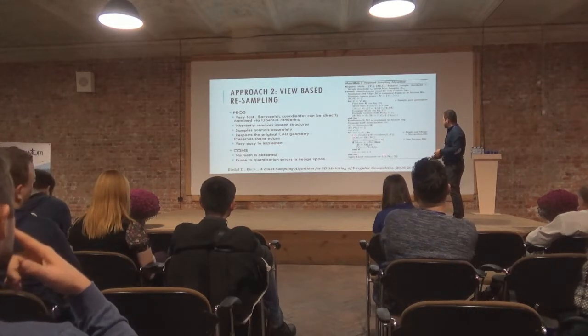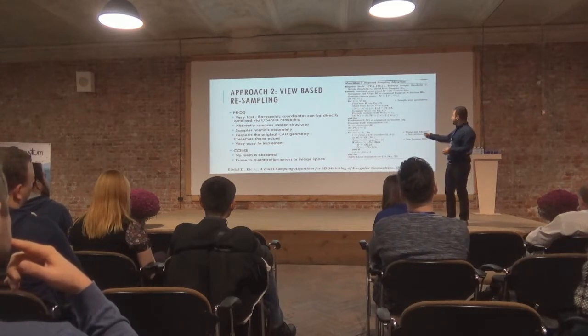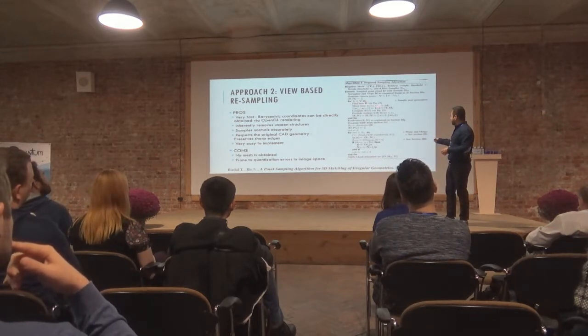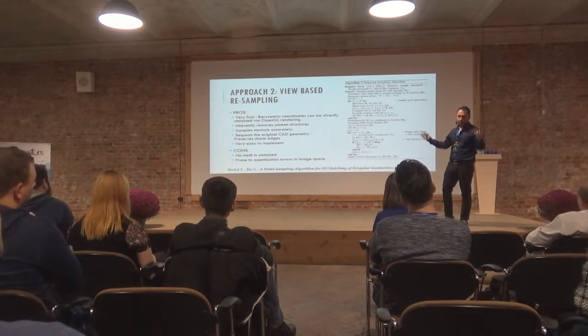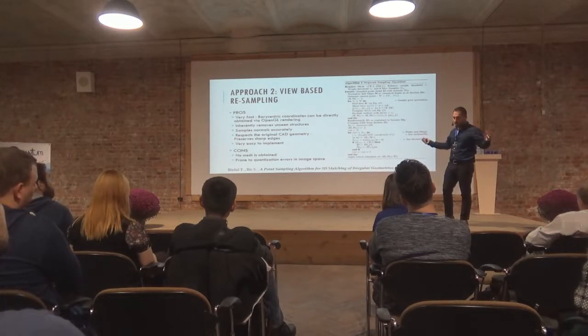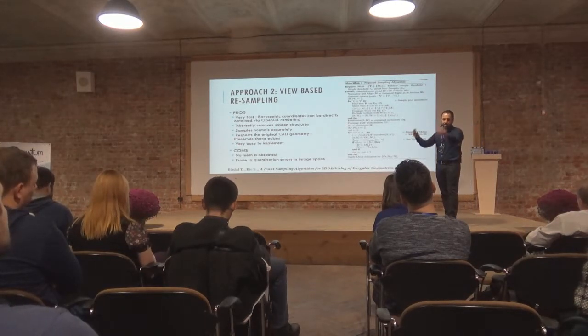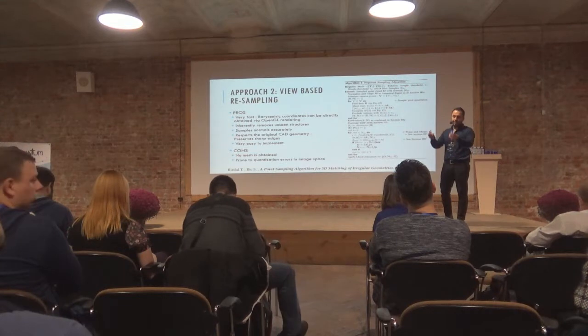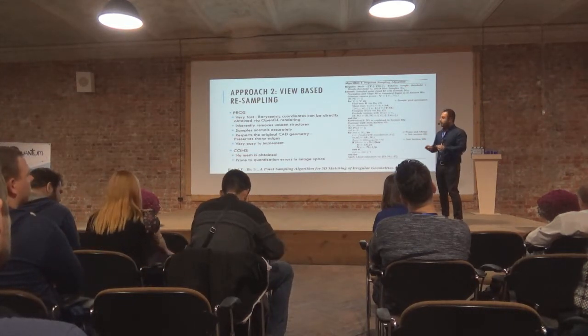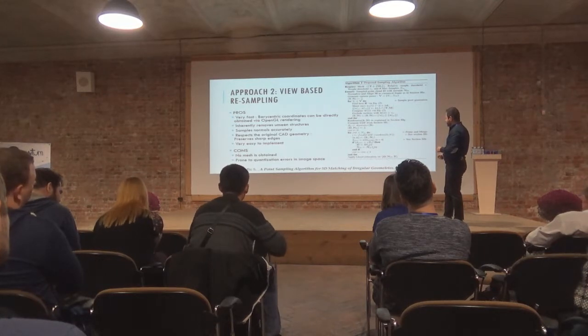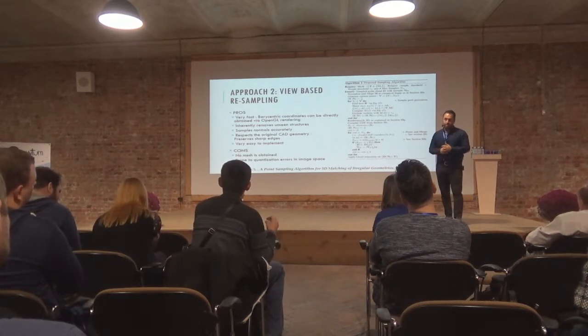Right, this is just the fusion part. I don't know if you want me to go through here, but you basically find the camera matrix and then shoot some rays, compute the intersections of the CAD model. So you go from the image space to the CAD space, intersect these things, and sample only the points where the image rays intersect the CAD model. And then you fuse them in a subsequent stage.